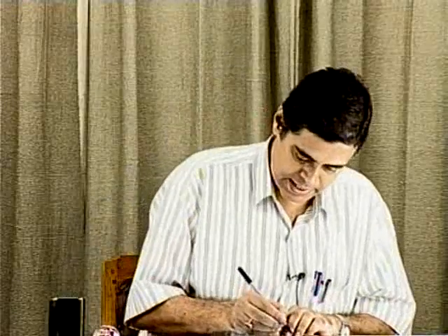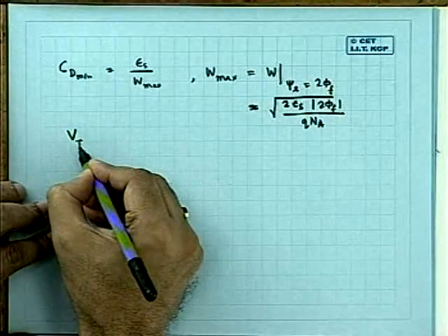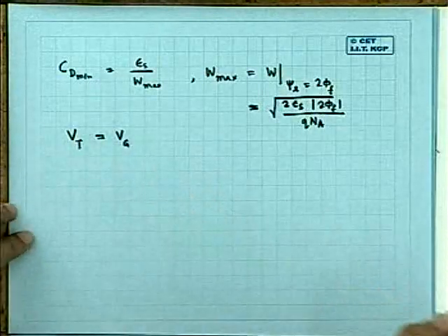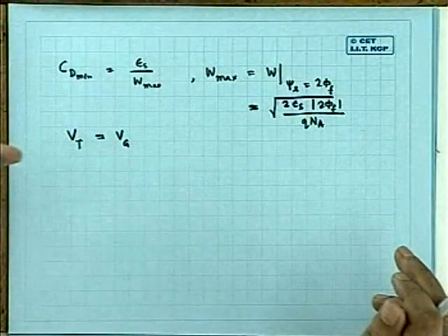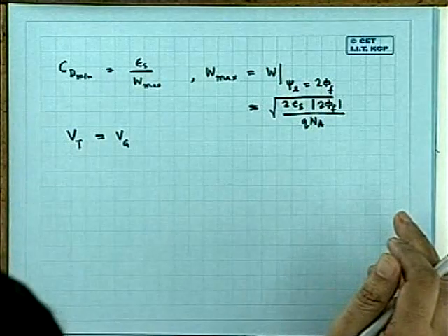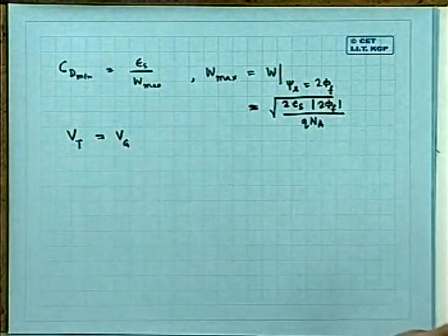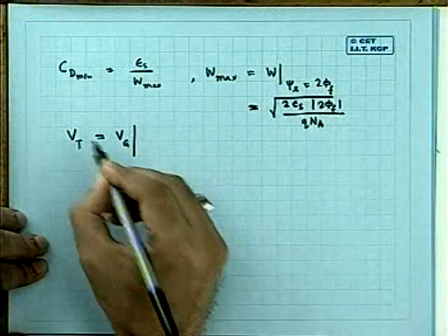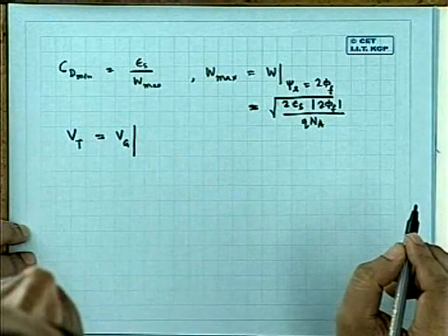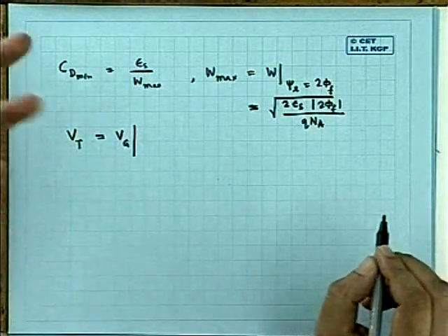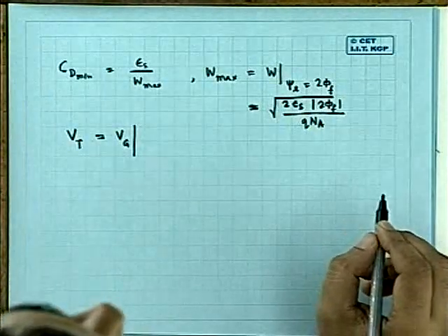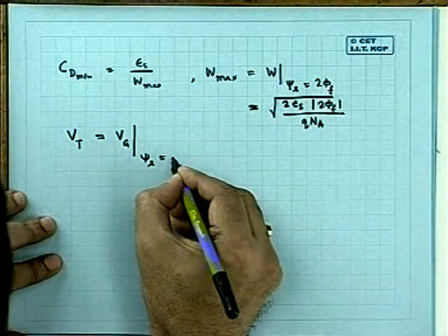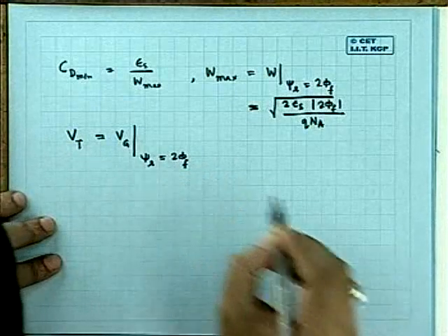Now, we have seen that the threshold voltage is a voltage. Let me come back once again to VG, because that's how we are treating VG. It's called a CV plot, so I have intentionally not written VT. So what is the definition of threshold voltage according to our simple way of visualization? It is equal to this when psi s is equal to twice phi f.